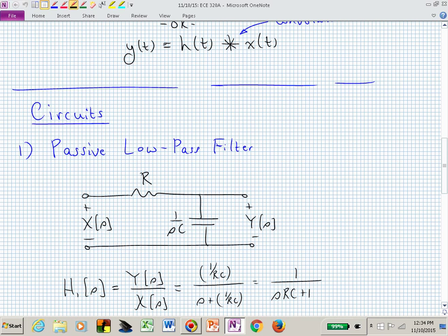But here is a low-pass filter. You can sketch that, and you can immediately, by a voltage divider using impedances, like you've used resistors in the past, find the transfer function either in the third formula or the fourth formula. And how do we refer to those two descriptions? The one closest to H sub 1 of s, how do we refer to that transfer function? What form is it in?